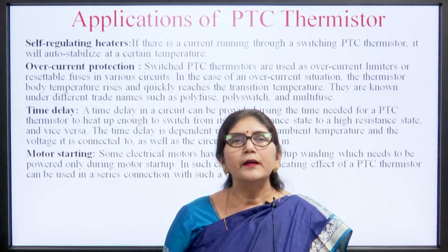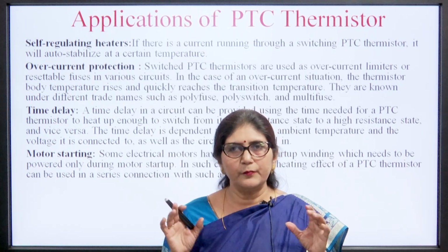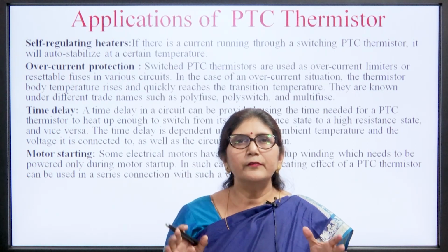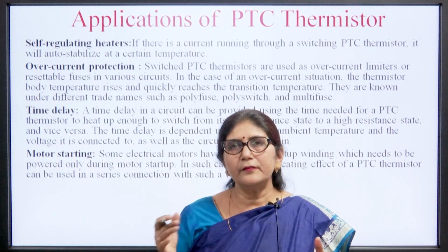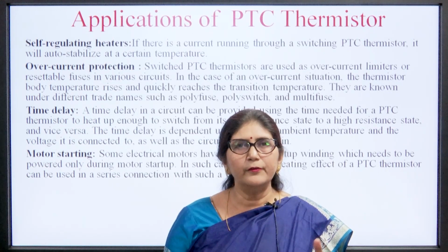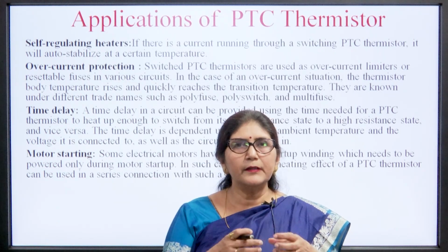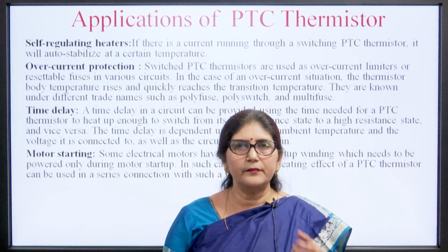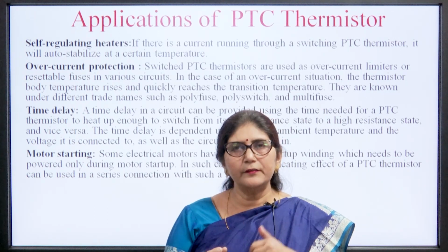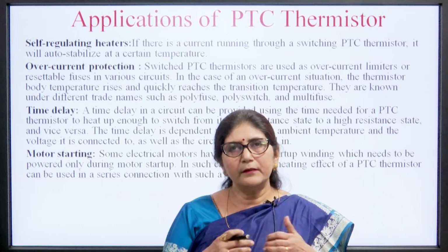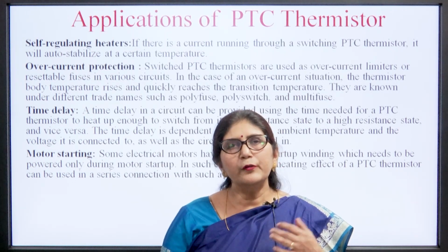Then motor starting. In many motors, we need a special type of winding, which is known as startup winding. There is a separate startup winding which needs to be powered only during the starting period of the motor. At that time we connect the PTC thermistor with that startup winding, so the current flows through the PTC and the startup winding, and a magnetic field will be induced and the motor will start.